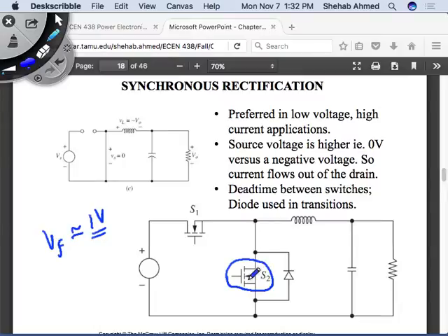It's exactly, you were talking about, remember we were operating these MOSFETs or BJTs in this region here. Remember the triode region of the MOSFET? We are operating along this straight line characteristic. This is the ID and then VD. And this slope here is equivalent to 1 over the MOSFET resistance, 1 over R. Remember that from 325? So this resistance is typically very small, because this slope is very high. So 1 over this slope is the resistance, and then it's a very small number.